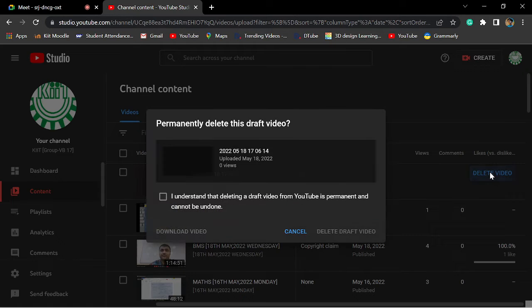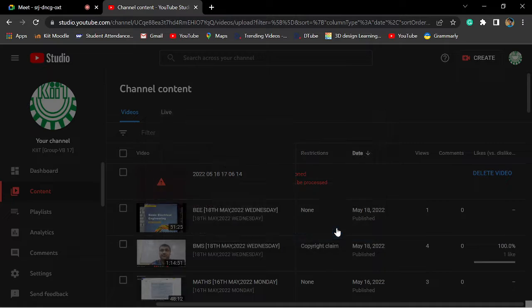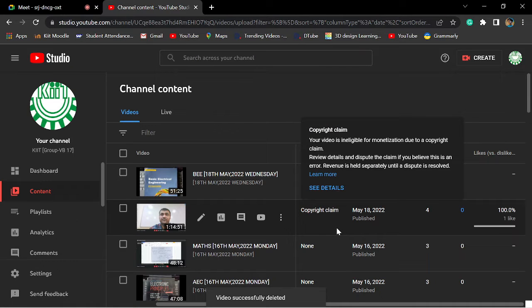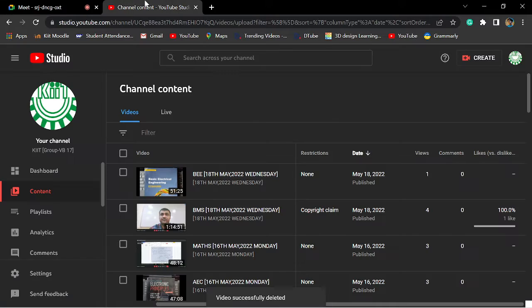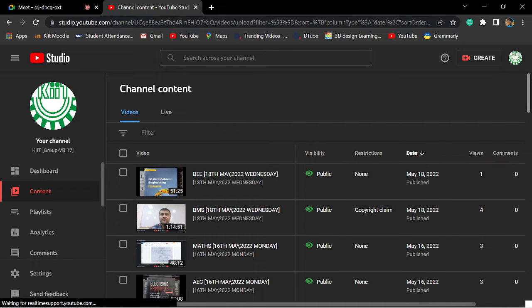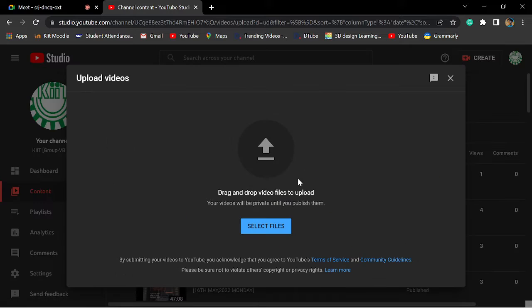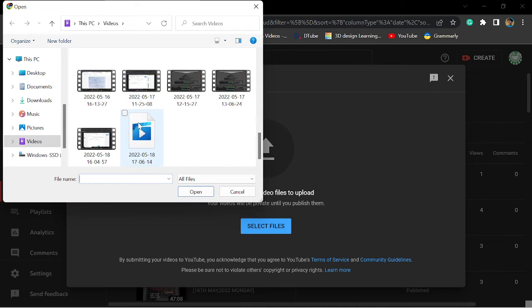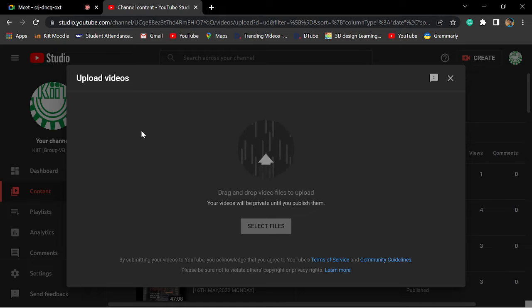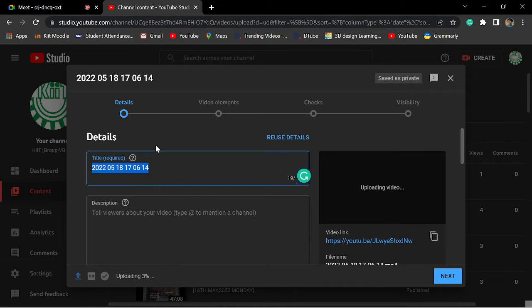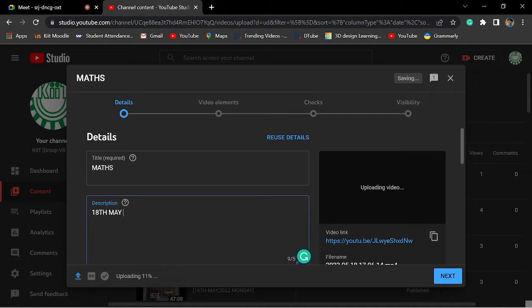Now if one terminal V1 is grounded, if V1 is 0, that implies V2 will also act as 0. Even if V2 is not grounded here, it will act as ground. So this is called virtual ground. If it is not grounded, then both the terminal voltages will remain the same. So this concept will be used along with KCL to see all the applications.